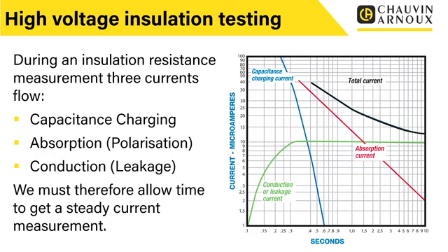So again, this is why it's important for us to apply the test voltage for a suitably long period of time to allow this to deteriorate to where it's not affecting the overall readings.